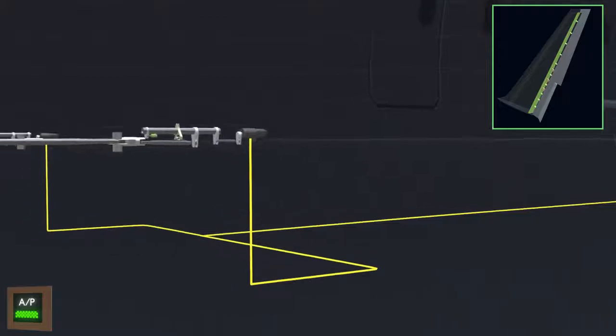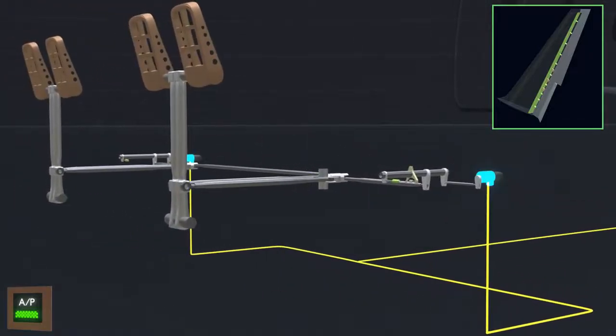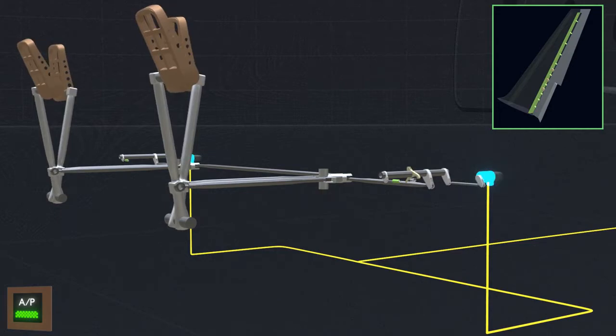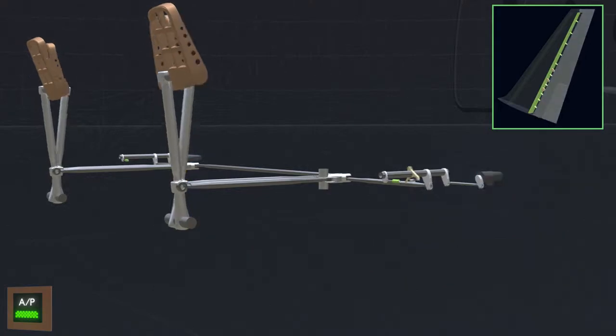The autopilot computer engages the back drive actuator and runs the motor to match the rudder pedals to the current rudder position. Back-driven pedals inform the pilot of an autopilot rudder deflection. Once the autopilot command is over, the actuator clutch is released and the pedals return to neutral.